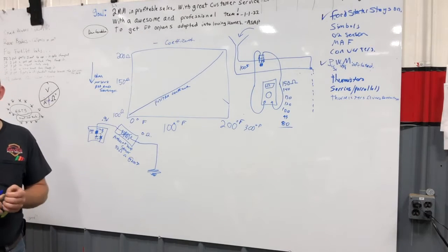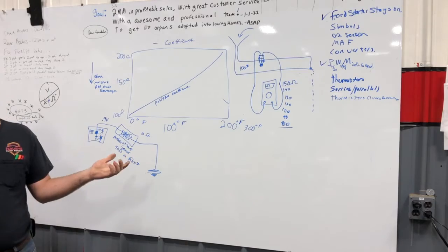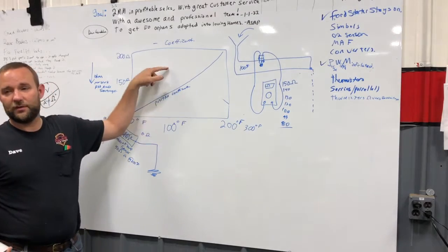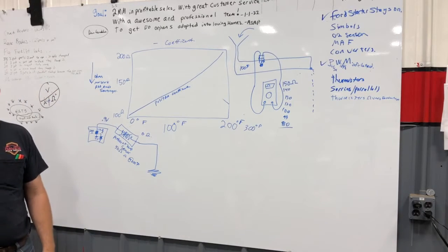Playing with them to see where they go. Honestly, by that you can tell if it's a positive coefficient or a negative coefficient. If you made it hotter and the ohms went down, you'd know it's a negative coefficient.